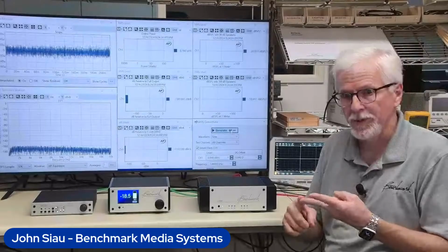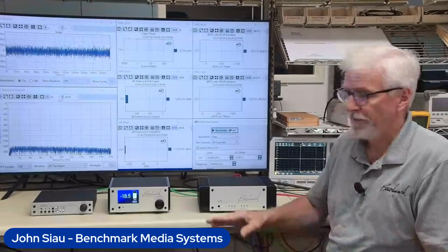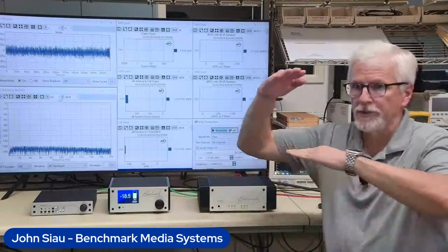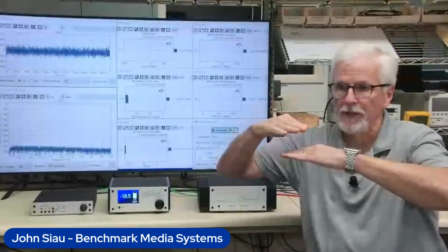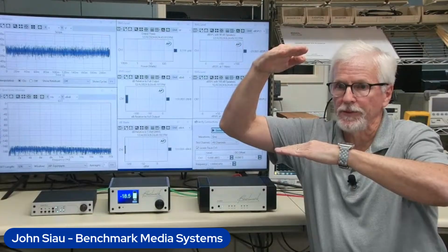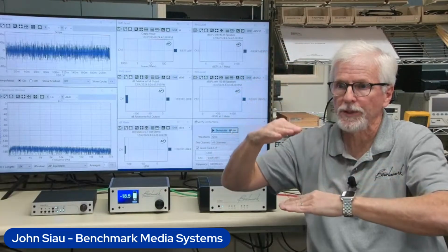And then you use one master volume control in the preamp, because the preamp is the lowest noise volume control out of the whole system. Because it's an analog volume control, it's doing two things. It's dropping the signal level and it's dropping the noise level. If I were just using a digital volume control, you'd see the signal go down, but the noise would not change. With this, they're both going down.